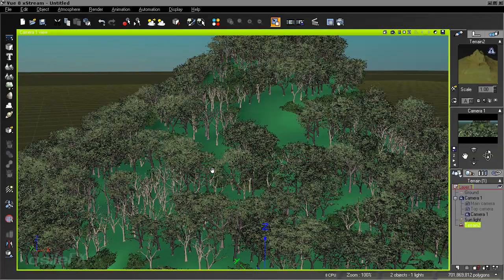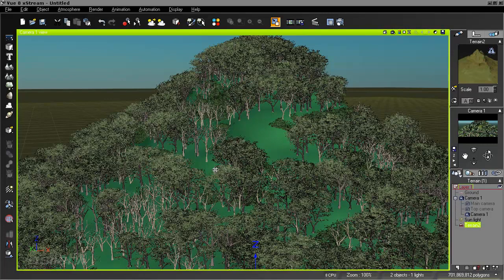So if we need to limit the amount of these trees showing, we have to go into the function and really work with that area and cut out the zone. That really might be a little bit too much work depending on the size of the scene and the amount of variation you need. And by driving it with a function, we lose the ability to just directly type in a number. So what we can do instead is work with multiple layers.